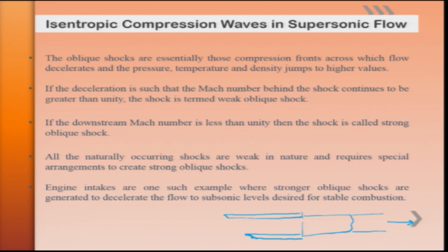A ramjet cannot fly on its own, and you require a supporting mechanism to achieve a particular Mach number, after which the ramjet can fly on its own. How is it possible? This is possible because of the intake or inlet present at the entry point of the ramjet.